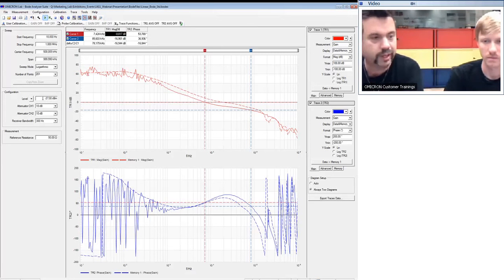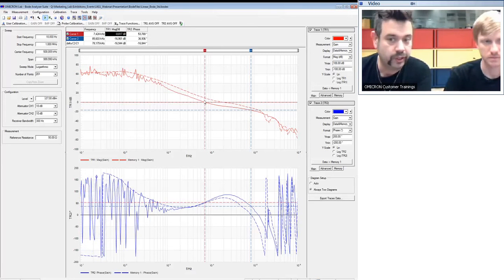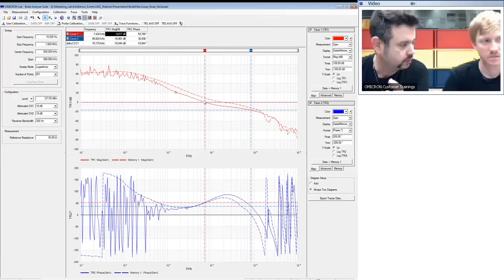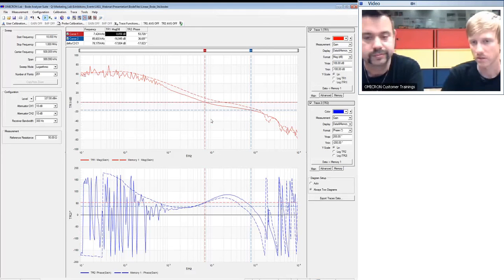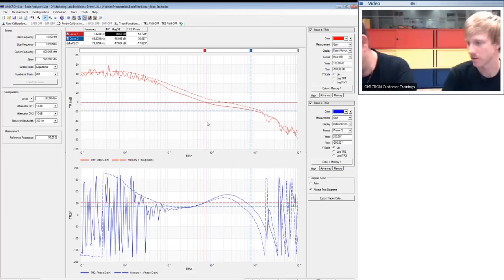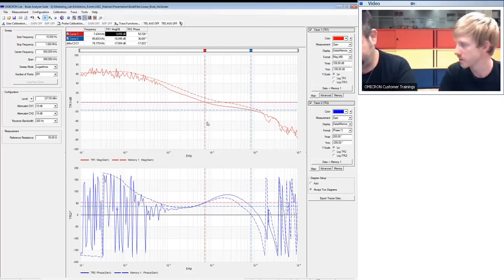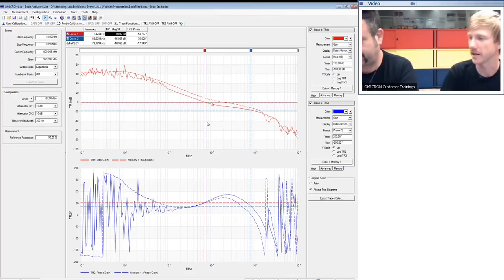But what would happen if we have to reduce the signal level further? We had some systems where we had to measure with a signal level of minus 47 dBm. What can we do in this case? Well, then you could add an attenuator, a real, physical attenuator between the output of the Bode 100 and the injection transformer, for example, to reduce the signal level further.